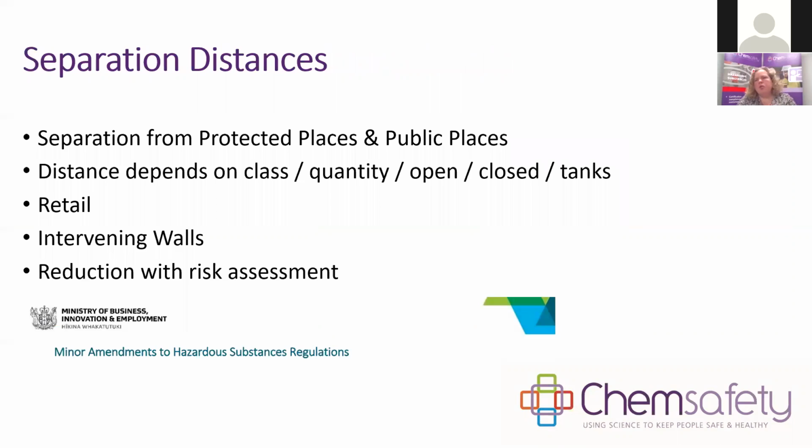These stores also require separation distances. This is probably the other major area of debate. So making sure that it's separated from protected and public places, depending on the class and quantity, whether they're open or closed or whether they're tanks. There are some provisions for retail premises and also for the intervening walls.